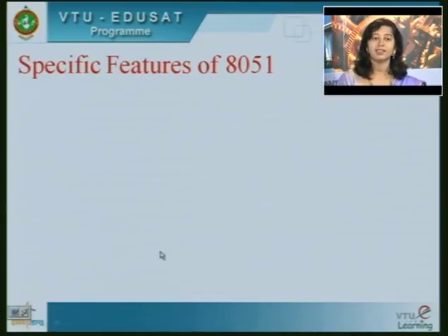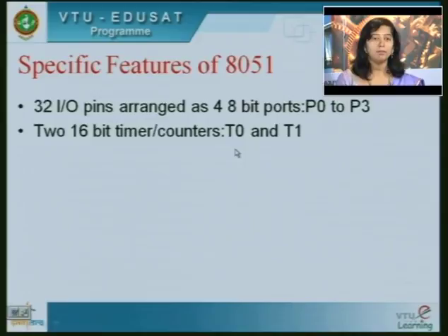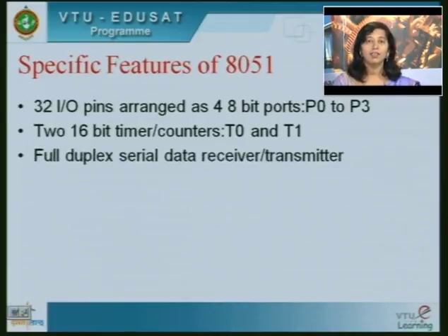These are the 3 things. Coming to the other specific features, we have 32 IO pins arranged as 4 8-bit ports, port 0 to port 3. Then 2 16-bit timers or counters, T0 and T1. A full duplex serial data receiver and transmitter.